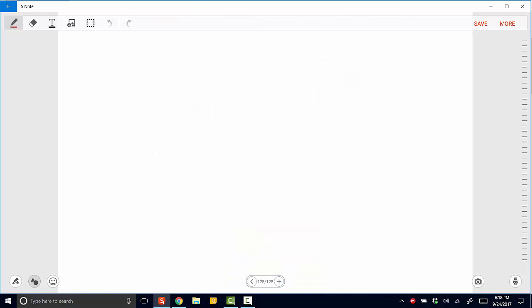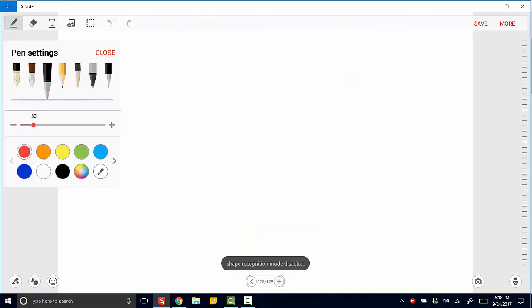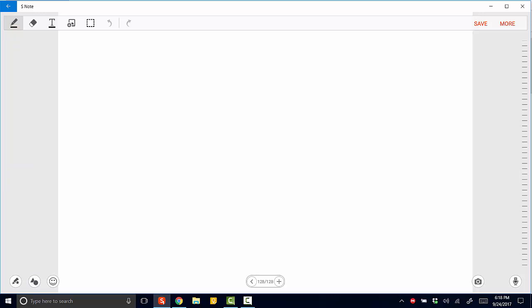Let's go ahead and note that sigma 1 is the larger value, 104.03 megapascal, and that's at an angle phi p equal to negative 25.7 degrees.